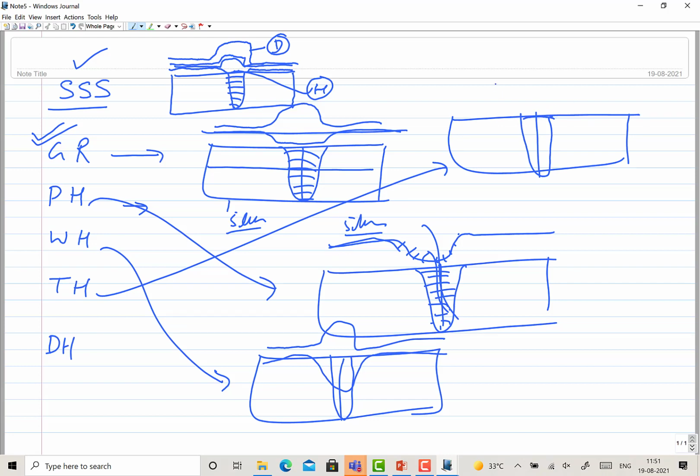That's very common, because both deformation and heat application in transformation hardening metals cause hardening, and that's why invariably you get a lot of change. So initially at room temperature you may have 200 HV, but here you may get 400 or even 500 HV. So this is contributed by transformation hardening metals. And about dispersion hardening I have already talked.